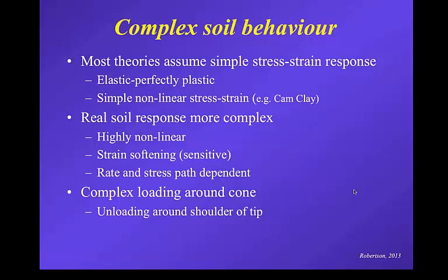So you're pushing the cone, there's obviously a load on it, there's stresses on the tip, and then when you stop, if you take the load off, of course the rods rebound a little bit, the load begins to drop on the tip, and so you pick up this unloading of the soil due to the release of the load on the cone. Based on that, often the recommendation is to keep the load on the cone. In other words, clamp the rods so that you do not unload the rods.